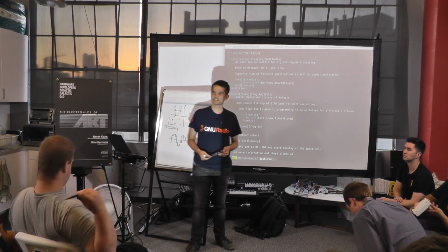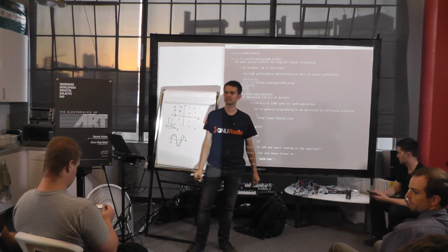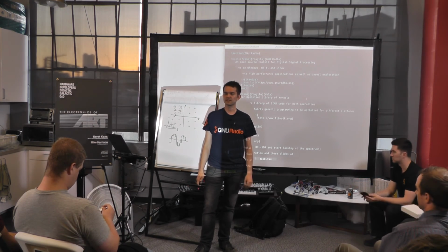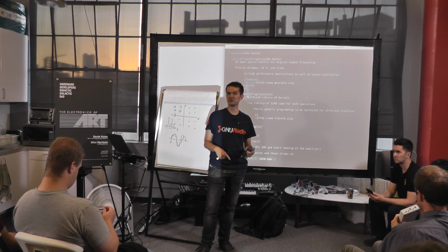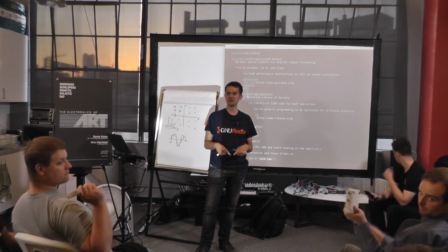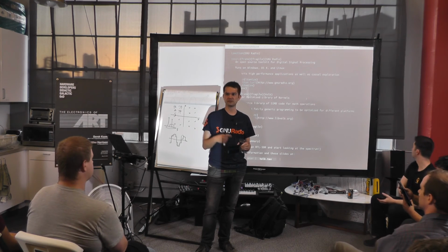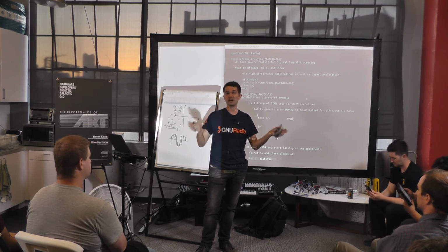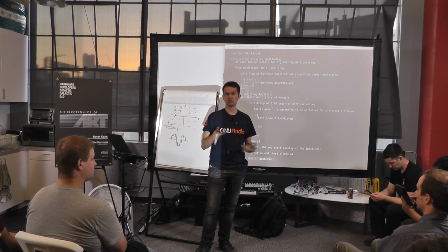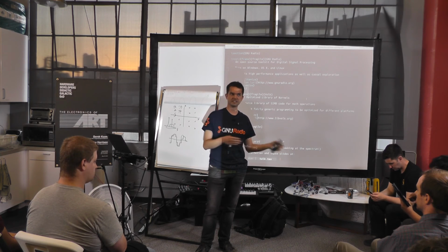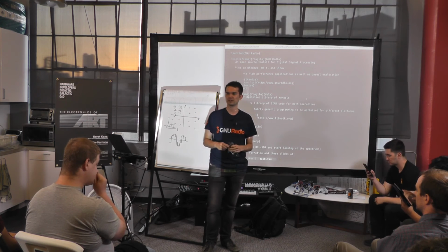Yes? Are there any general rules of thumb for data rates compared to frequency and encoding versus really complicated constellations? Sure. One of the things I didn't get to was, if you have one of these that will transmit, be careful where you transmit, because a lot of the spectrum is licensed. The Federal Communications Commission considers the wireless spectrum to be a shared public resource. And so the limitations on what you can transmit come both from physics, but also the FCC will say you can only use this type of modulation in this frequency range.